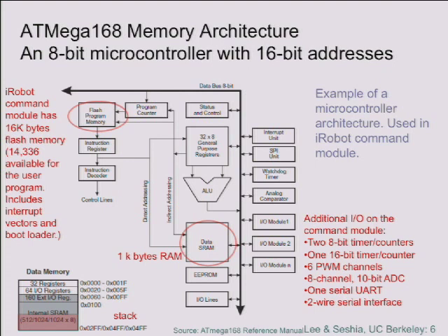At that point, you may also put local variables on the stack, okay? Meanwhile, your stack pointer keeps going up, okay? And each time you do a procedure call, your stack pointer goes up, which is actually down in addresses, right? What happens if you do too many procedure calls? Your stack pointer will start writing to these external I/O devices, which aren't provided, by the way, so what happens when it reads those values back?